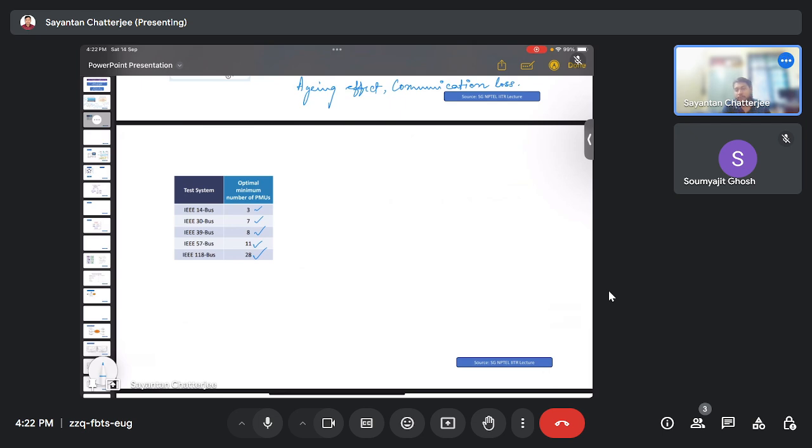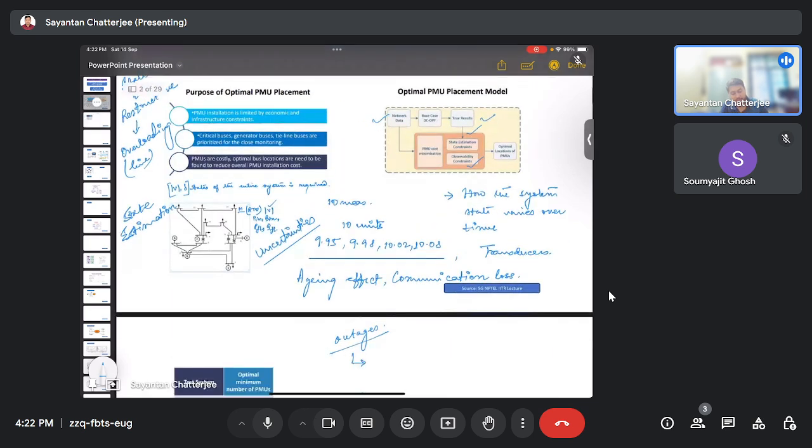So if we want to consider the outage, we also need to take other constraints like system outages. If we consider these outages, the number of PMUs placed will increase, not might, it will increase, because some lines could be tripped, for example if suddenly there is a fault and this line is out. In case a PMU placed here is making this line observable, that won't be the case now.